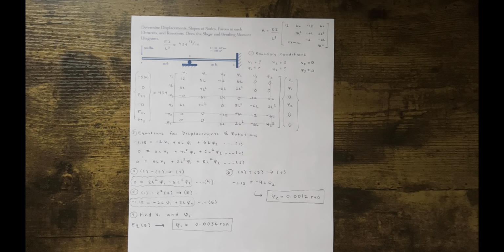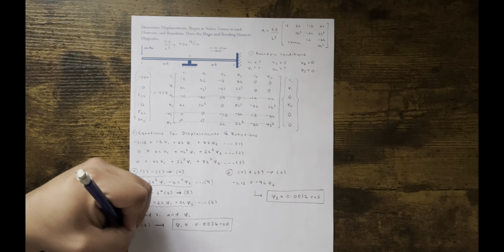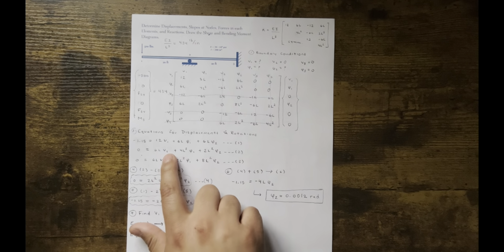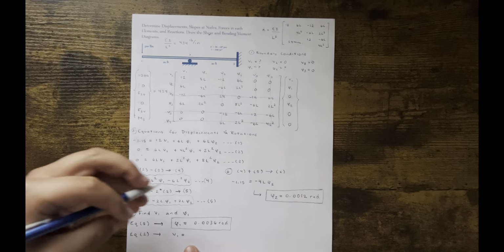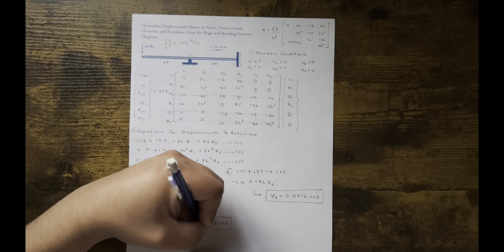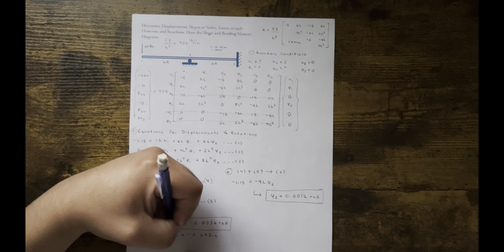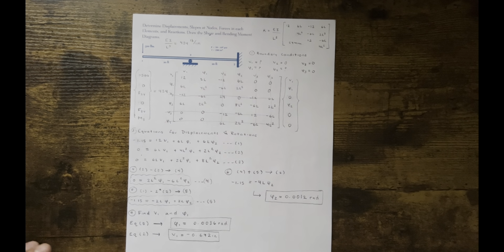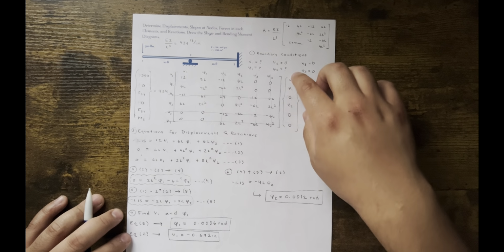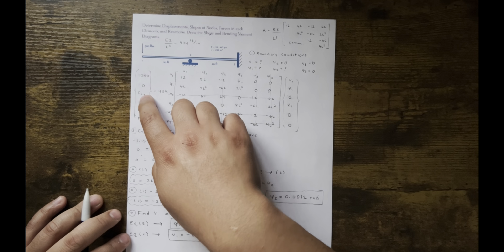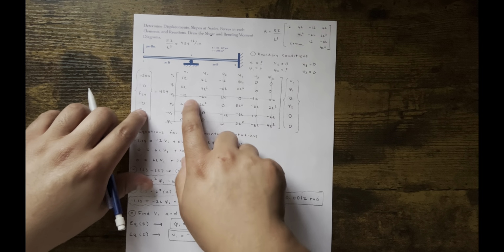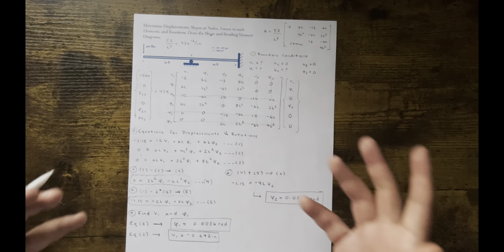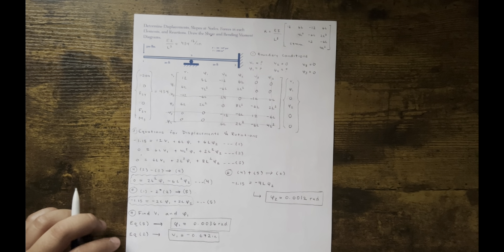And then equation 2, I just chose equation 2, it doesn't matter. You'll find that v1 will give you negative 0.672 inches. And just like that, we found them. Once you find this vector, now you find this vector: in this case, F2y, F3y, M3. We have all this, so using this same method in step 3, F3y is equal to 6L v1, blah, blah, blah. You should be able to find F2y, F3y, M3. Let me do that one real quick.